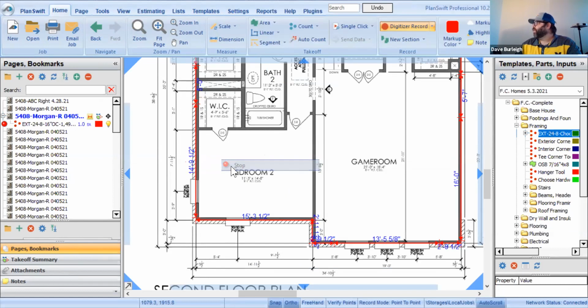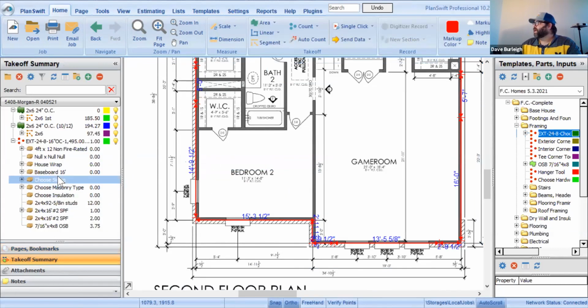then when I count that wall type, I can now see that to make that wall, I need 12 2x4 by 92 and 5/8 studs. I need one 2x4 by 16 for my bottom plate. Then I need 2 additional for my top plate. And I need 3 3/4 sheets of OSB to cover that specific wall section. Again, that lets me then hone in my material list because I've already solved this is what it takes to build that wall.